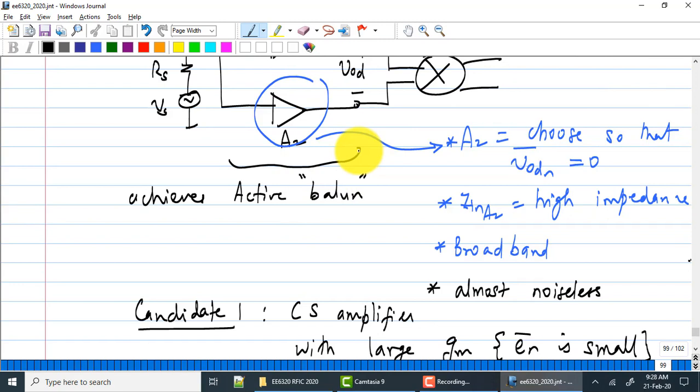More importantly, the two output impedances are not the same at all. Actually, the two outputs are completely asymmetric. That's what I'm coming to. The two outputs are completely asymmetric. That is one big problem with this noise cancelling LNA. So let's look at that now.